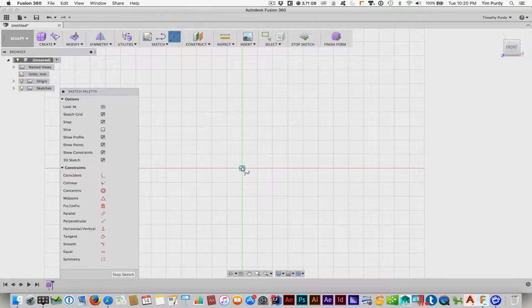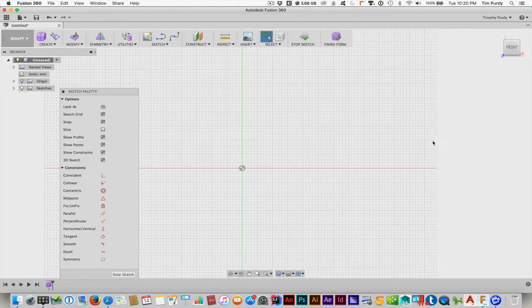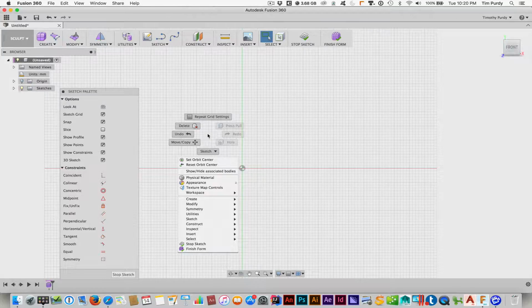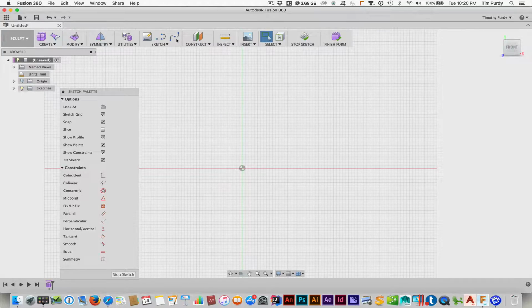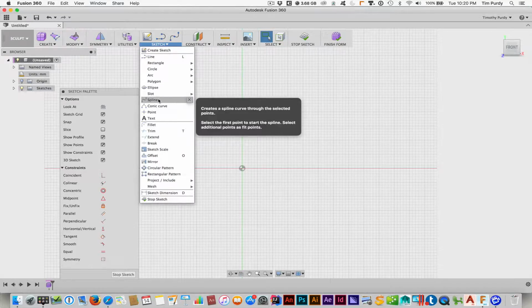I want to make sure I can snap as I do this. I'll come out, say about right there. Now, right now my grid's actually a little bit too big, so let me undo this real quickly. Go down here to grid settings, and let's do 5 so it won't be super dense. Alright, there we go. Let's see, back in and do once again a spline tool.